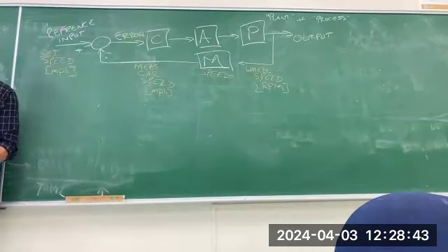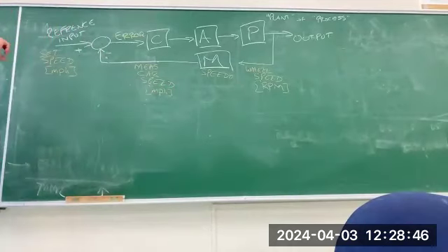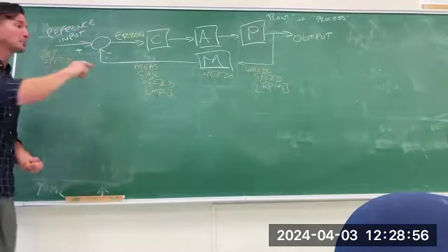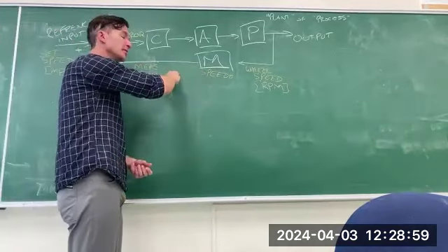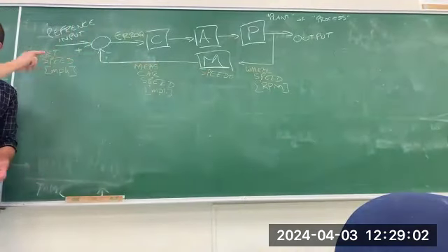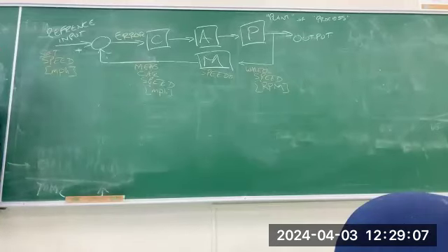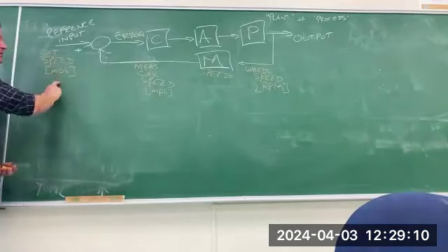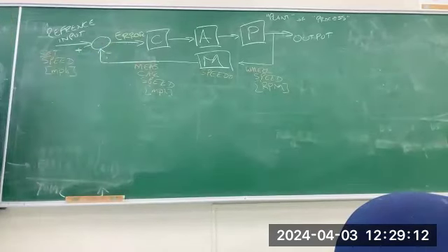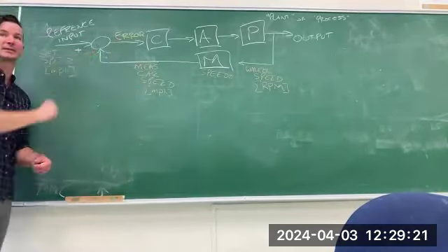Okay, this highlights a very important aspect of block diagrams, which is what we're creating here. When you add or subtract signals, they have to be in the same unit. Right? If you had opted for a digital speedometer, whose output would likely be a voltage, then I would have said, I gotcha, because we can't subtract voltage from MPH. But you've seen through my ploy. This is MPH, this is MPH, so this is the error measured in miles per hour. Is the car going too fast? Is the car going too slow? Whatever is happening here and here affects this signal.